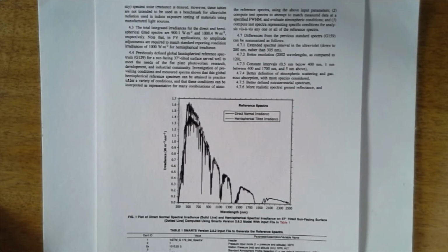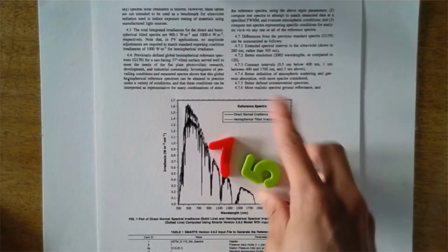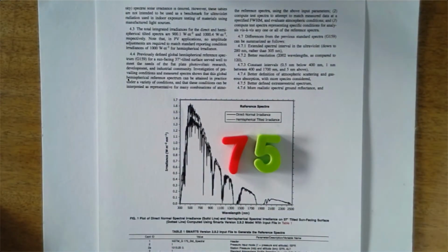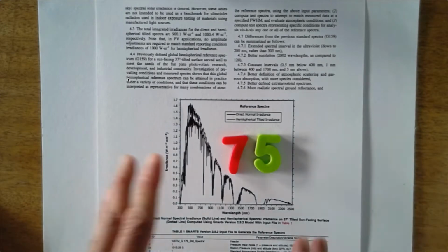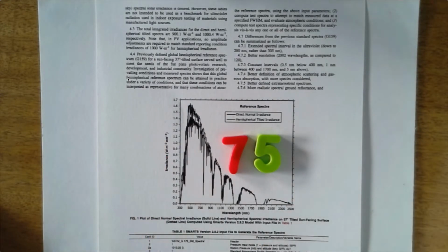Previous studies have shown that there can be up to, if I can find the number, 75% deviation in the simulated energy yield between assuming this fixed spectrum and actually using a real solar spectrum when we estimate the power that's being generated by one of these. So moving forward, it's quite important for us, when we design multi-junction cells, to not use these fixed solar spectra and instead use spectra that are based on real observations and real climatologies. And this is where we can come in.